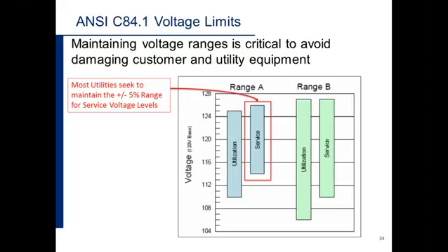I've asked utility engineers around the world about this issue, that's my background before coming to the lab, and I think that it's pretty universal. Utilities strive to keep their voltage within limits. Plus or minus 5%, it may be a little broader than that, but if voltage gets out of range by too far, we know that equipment can be damaged, and the utilities don't want to see that.